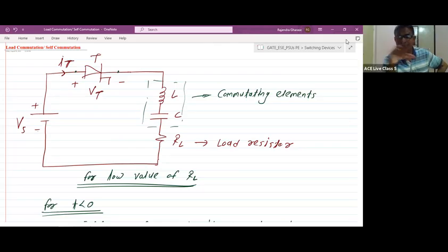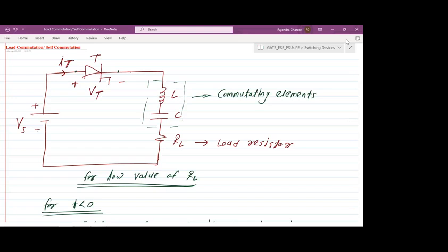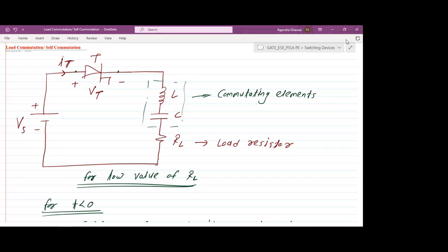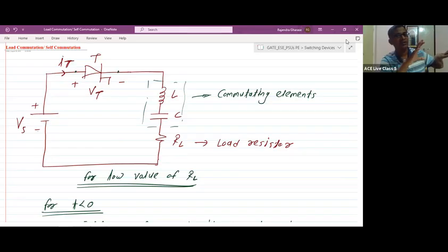Because it is not like that after one cycle we are stopping now. In real life, suppose if you consider the inverter circuitry, and suppose the inverter circuitry is having an output frequency of 100 kilohertz, then you can imagine in 1 second we require 100k cycles, na? So after one cycle, one output, our SCR should successfully turn off, and again for getting the next output cycle, the SCR should again turn on, na?